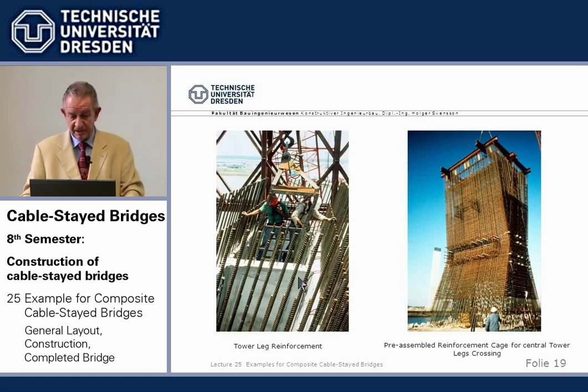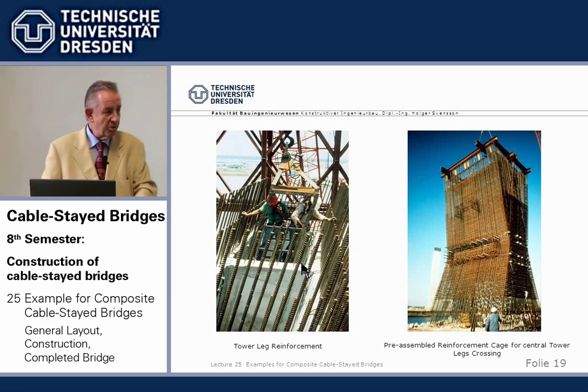Just to give you an idea that we were really squeezing the thing, we had 2.1 meter wide tower legs, 30.5 centimeters thick, which of course is 1 foot. And then we had two horizontal and vertical reinforcement inside and outside. So we had in the 30 centimeter thick walls 4 layers of reinforcement, 25 millimeter diameter. So it was rather a little bit tight, but it worked.